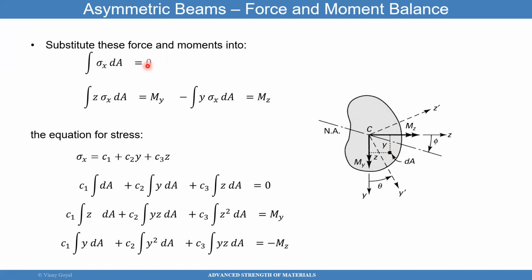Then I can now calculate the moment about the y-axis. If I choose this point here, then the height is z, and sigma xx is out of the page of the plane. When you do that, you get a positive moment in y when you integrate this over the whole surface.